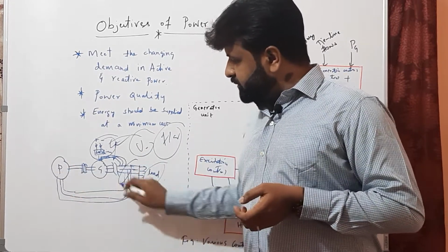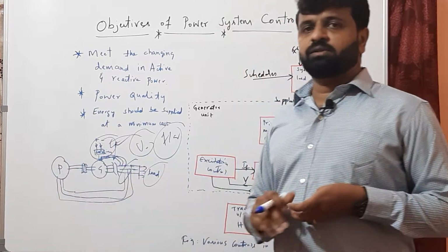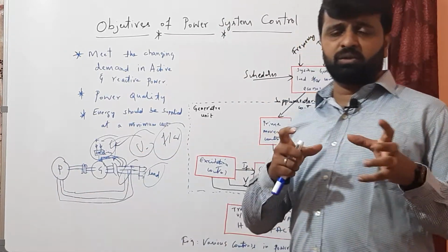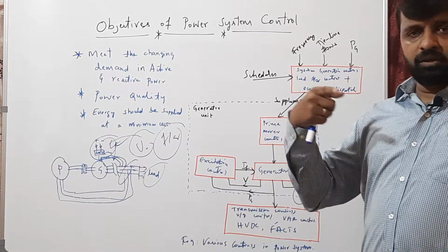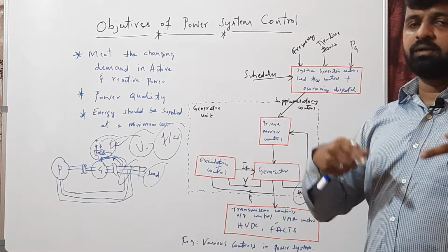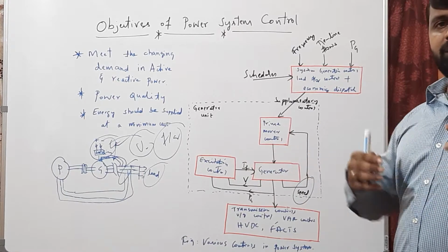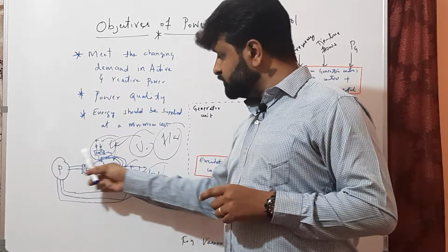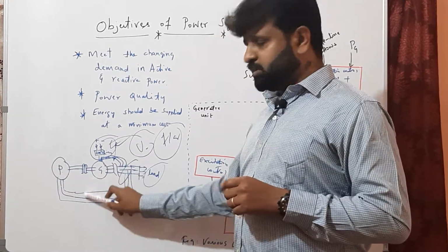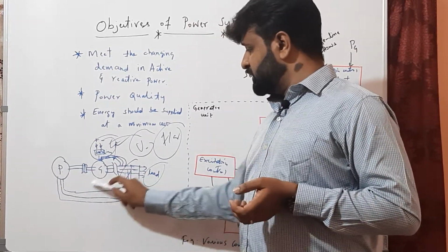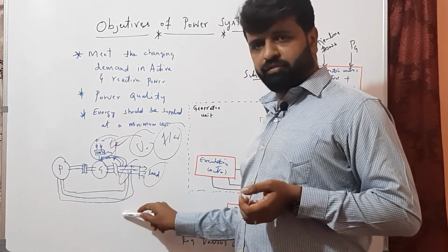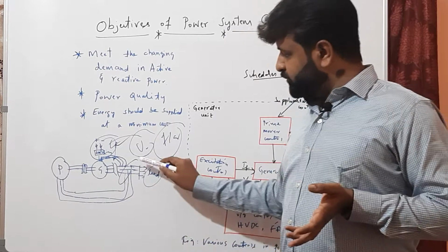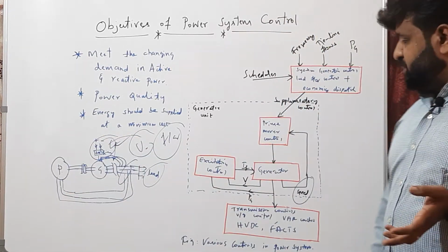Again, we take the feedback of this and connect it back to the system. For the prime mover, if it is a hydro power plant, they use servo motor control for the water jets to control the speed of the turbine. In a thermal power plant, they control the steam of the turbine. Based on that, control systems like embedded systems, electronic devices and certain software like SCADA systems and AGC are involved, especially AGC, in controlling these things.